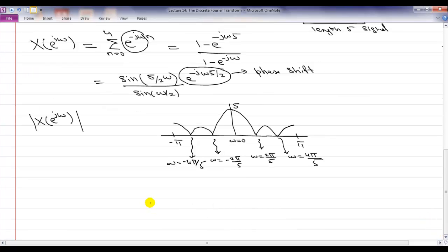Now, as I said, you could have computed the DFT of this thing explicitly using the DFT formula, and you can do that. But right now, we want to interpret the DFT as samples of the DTFT. So let's ask ourselves, what is X of 0, the zeroth coefficient of my DFT? Well, from definition, that is equal to X of e to the j omega at little omega equal to 2 pi 0 over N. Now, what N do we want to use? What point DFT are we talking about?